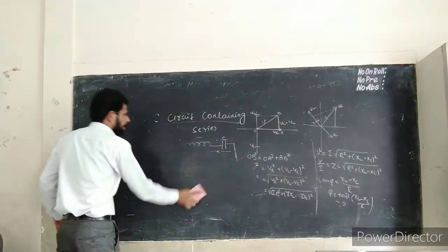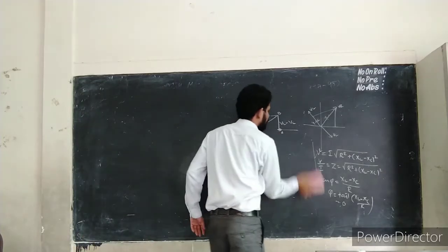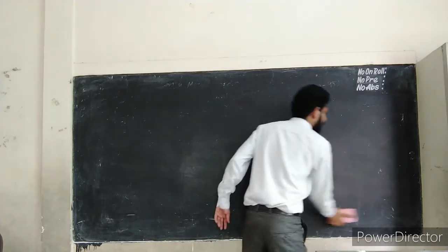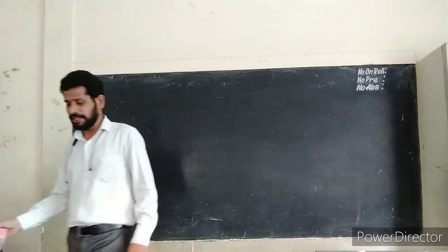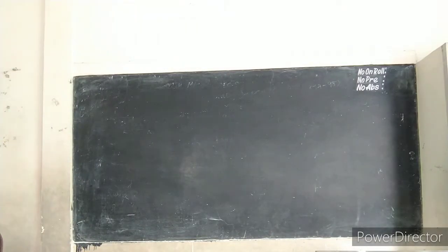So next one thing. What is called resonance? Or what is meant by the Q factor? Or what is meant by the resonance of the circuit? Resonance of the circuit is when the frequency applied by the alternating source is equal to the natural frequency in an RLC circuit, the current in the circuit reaches the maximum value, and then the circuit is said to be in electrical resonance.